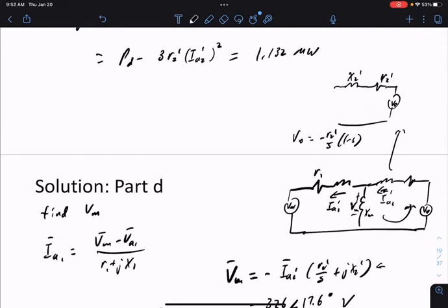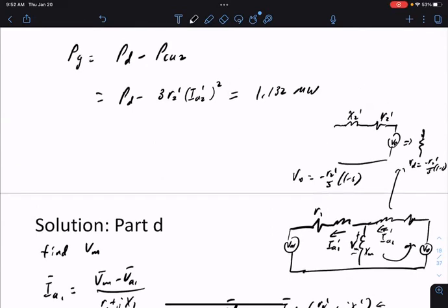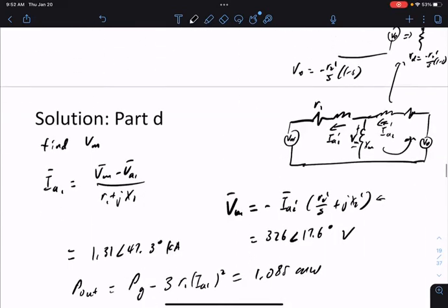So this is equivalent to some developed resistance R2 prime S over 1 minus S. That's why we get this equation here. This part is testing that, once you convert something to an equivalent, can you convert it back? And can you look at this current divider?